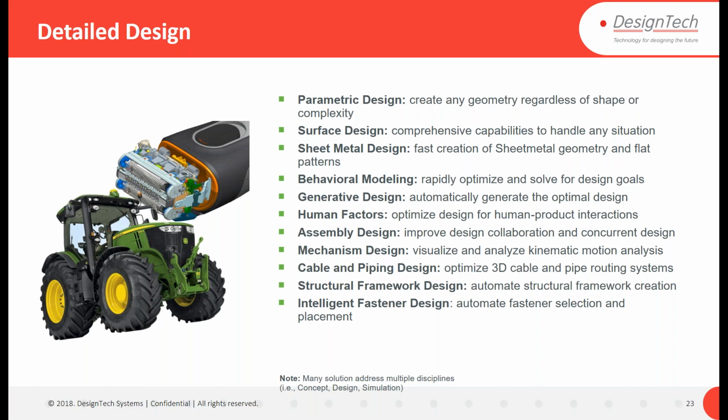You just have to choose from the library, create a sketch to define the structures, select the line in the sketch, and automatically the structure will be placed. There are different cut options, where it will cut where two structures are intersecting, based on what kind of options you have chosen.